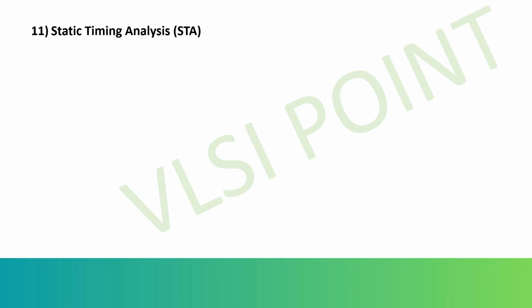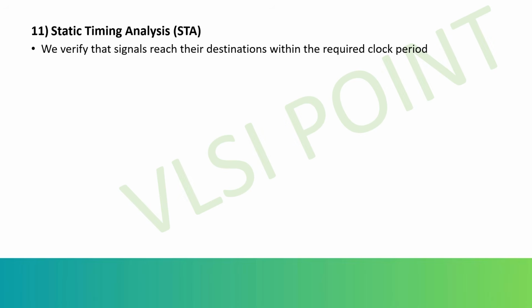Next step is static timing analysis, that is STA. So now we confirm that timing requirements are met for every path. The checks are setup time, that is data arrives before the clock edge, then hold time, data remains stable after the clock edge. Critical paths, like the longest delay between registers, determine the maximum clock speed. For STA you can use Synopsys PrimeTime. And remember guys, there will be no simulation, purely mathematical analysis of delays during the STA.